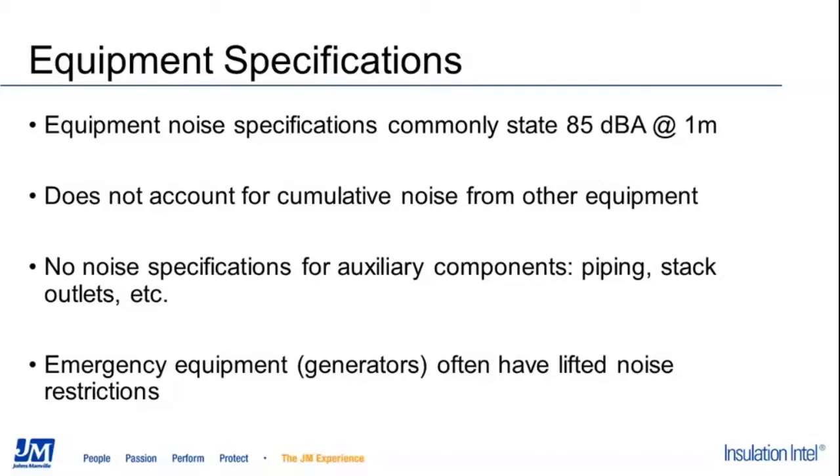Typically, there are no noise specifications for anything that may be attached to or connected to those pieces of equipment. So any piping, stack outlets, structural steel elements that may be holding the equipment. So you may have to take those into account as well. And then you will need to also be cognizant of the fact that very often emergency equipment, so pieces of equipment like generators, often are exempted from those limits because their operation is critical for other reasons.